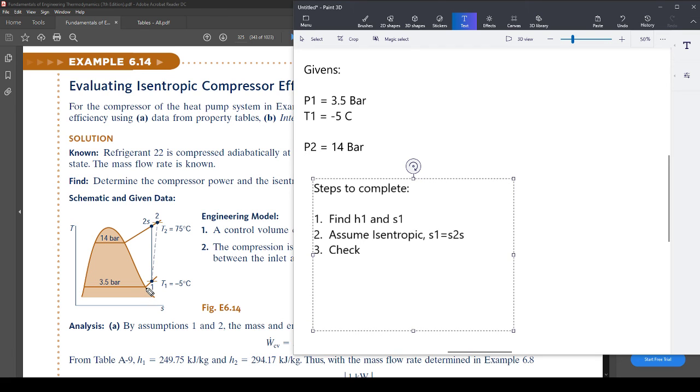So that means at minimum, state 1 will be right on the saturated vapor line. Or you can't put a lot in there, at least. And then if you go straight up from here, or on an actual, you'll go up to the right. There's no way. It can never go back to saturated. So it's always going to be superheated at the check. But I'm just going to say this is a good habit. Check the state. So this will be superheated, etc.